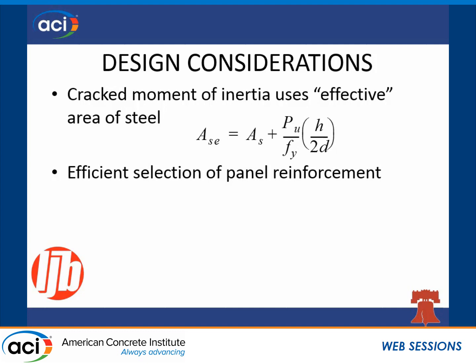And in order for the tension in that primary reinforcement to be engaged, it has to go from that compression through zero and into the tension. The h over 2d is an acknowledgement of the fact that that compressive force is dependent upon the location of the steel. The more the steel is centered within that panel, you can rely completely on the compressive force. The more it gets out to the outside faces, you can see that can be almost up to half contribution.